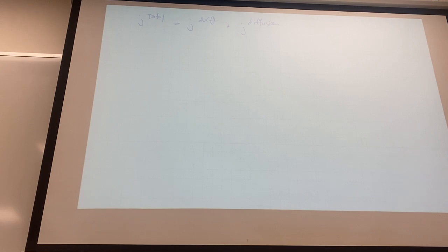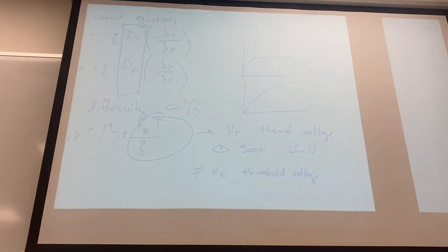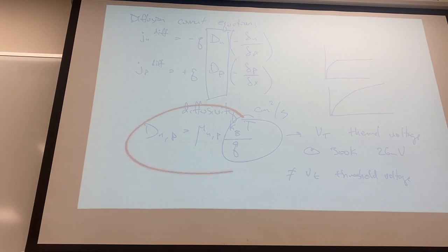All right, so that's drift and diffusion, and I'll add actual expressions now. So J total for n-type. If you take the expressions we've written before, do some substitution. I'm skipping a couple of steps here. We've got stuff like this diffusivity constant we can substitute into these equations. We wrote current density equations for drift current earlier. Just take it on faith that I've pulled those out and rearranged some expressions.